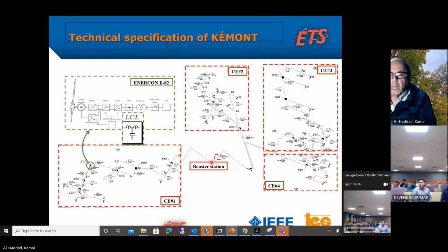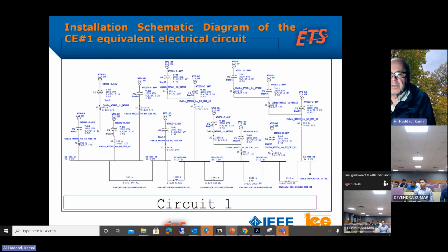Now, what's the problem with all these wind turbines? The filter. Why is the filter a problem? Because the filters are reactive components that are distributed all the way here and interconnected together. So imagine this network here with all those impedances to which we are adding those filters. If I remove the wind turbine and replace it by the filter, which is the case, I will end up having this network.